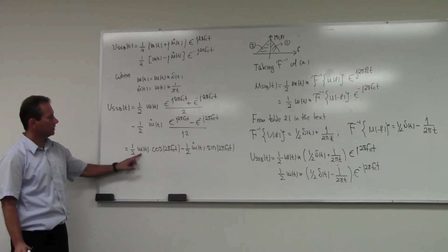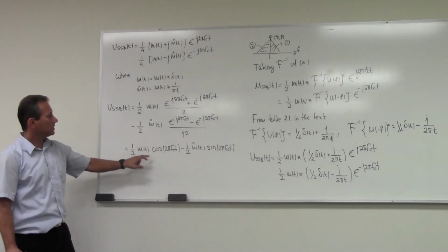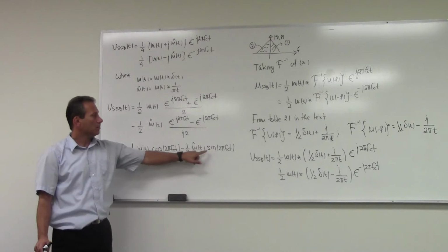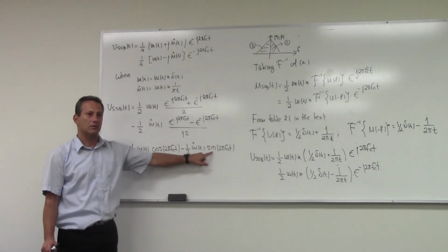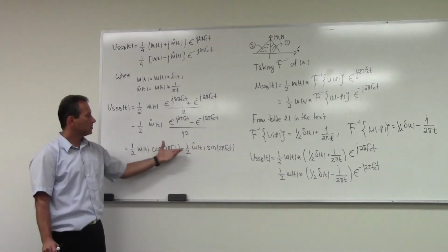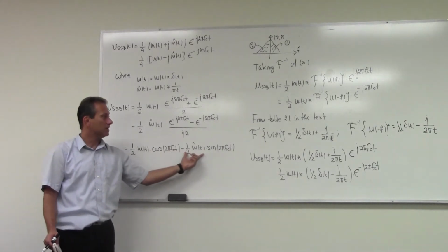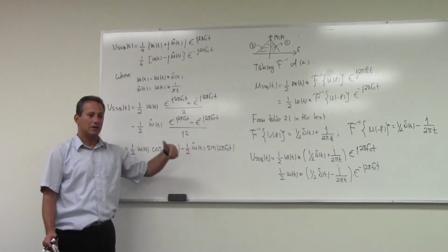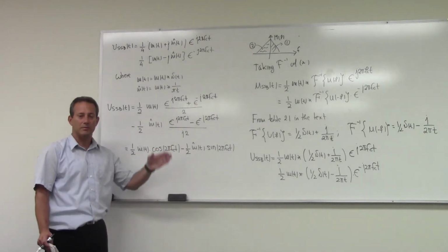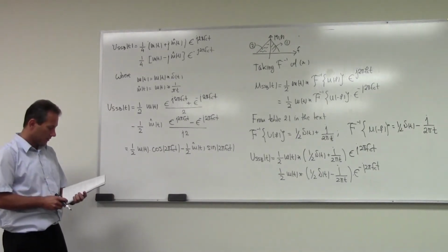You have to take your original signal and do your double sideband thing, just like double sideband suppressed carrier. You have to take the same signal and filter it somehow and modulate that using the sine now, which is the same as the cosine but just shifted by pi over 2, and add these two signals, and somehow magically they will cancel the lower sideband at the carrier frequency. You're doing all the processing here at the baseband, but when you translate this, it will actually remove the lower sideband from the spectral content of the signal.